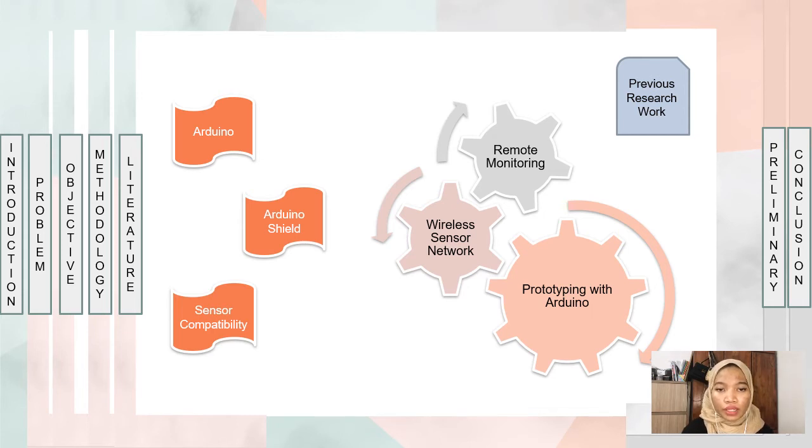For this project, I have done lots of research and I decided to use the Arduino Mega as my main component. There are different types of Arduino and I chose the Arduino Mega 2560 because of its specification. The Arduino Mega 2560 has a big dimension, a 16 MHz powerful CPU, 54 input-output capability with large memory size. For the Arduino shield, I chose the ESP8266 as a Wi-Fi shield module because it is low-cost, compact in size and has integrated device interoperability.